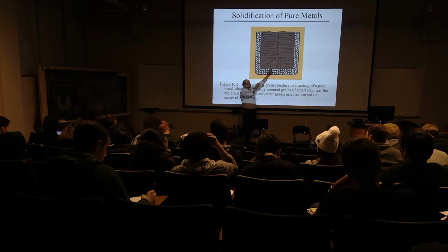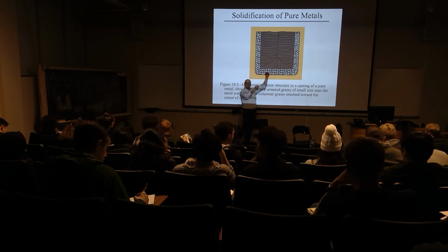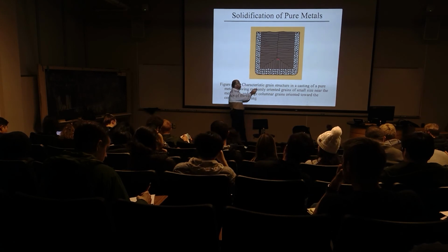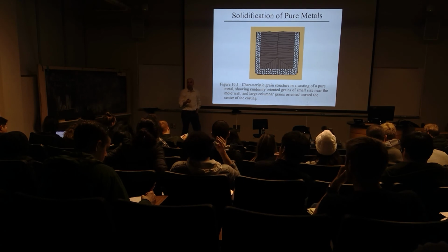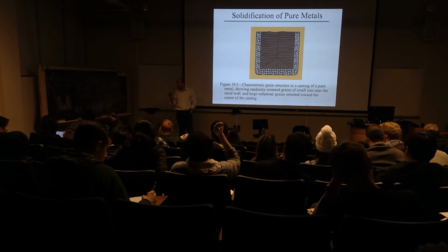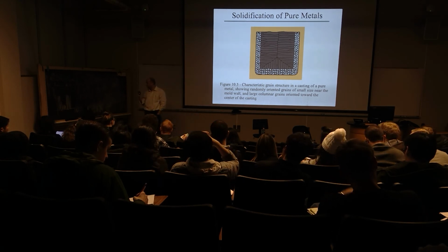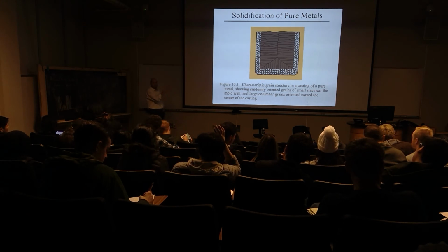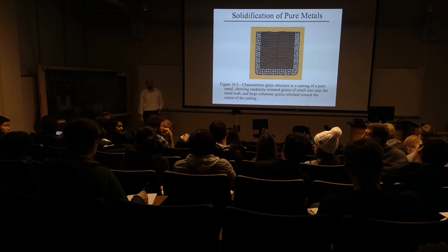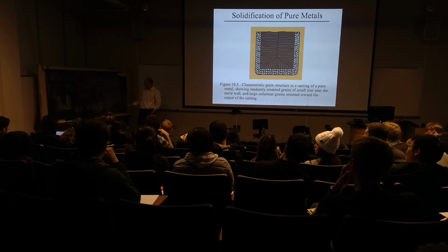And then also right at this point you have an intersection of grains. So you also know that in this case these will likely be areas of triple junctions, and those triple junctions will have more intermediate points or more locations, which is potentially an interface that can be weak. Is that sigma equals sigma naught plus K over square root of D?